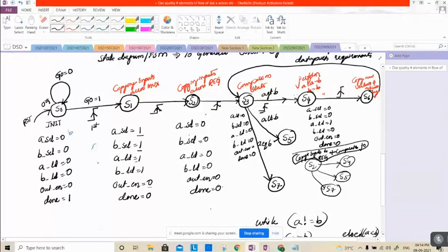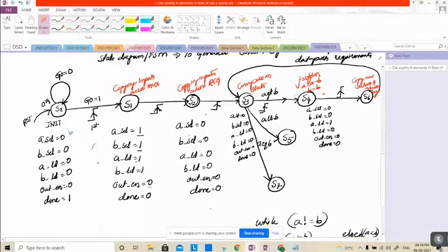Sir, I mean, can I go from S4 to S2? Why repetition? What is the purpose of S4? At S6 also there is loading, sir, so S2 also does the same work, sir. Right. Yes, absolutely. So the S6 state can be eliminated. S6 is going to load the new values of A comma B, whereas S2 is loading the initial values. Only that thing is different.